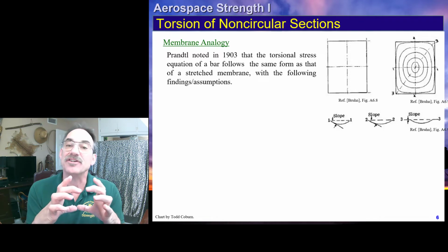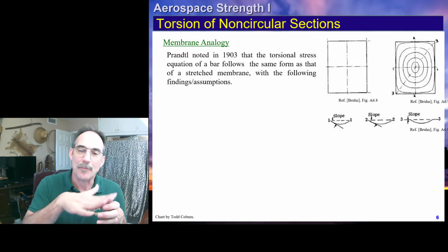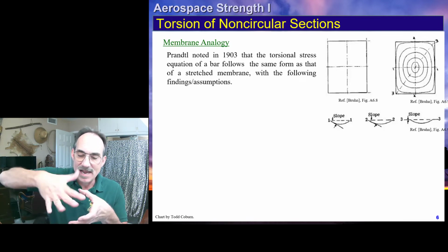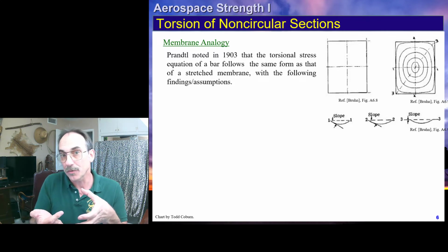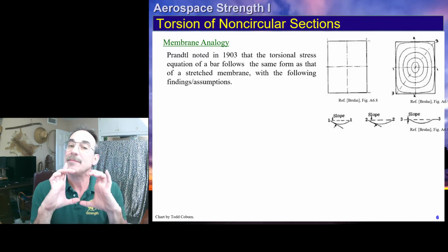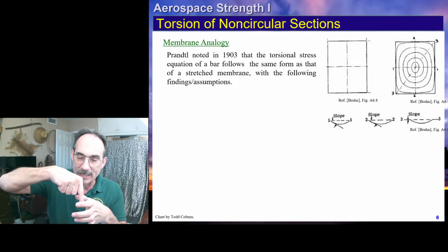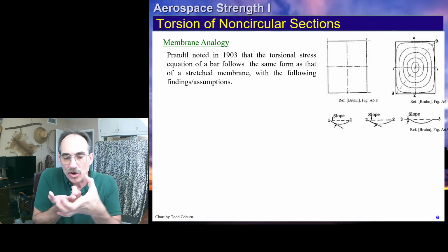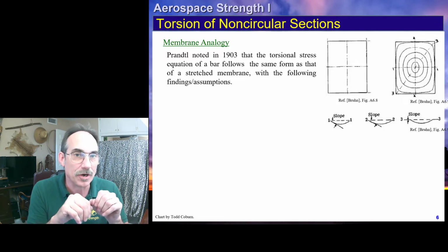Now imagine that you have a square frame and you have a thin balloon-like material and you apply pressure. Now if it were a round boundary, it would have a nice uniform depression down to the maximum value. But if that frame is square, you can see that you're going to kind of get a circle, an inscribed circle, into the smaller dimension, but as you get near the corners, you're going to get a little different. It's going to tweak up the deflected picture.